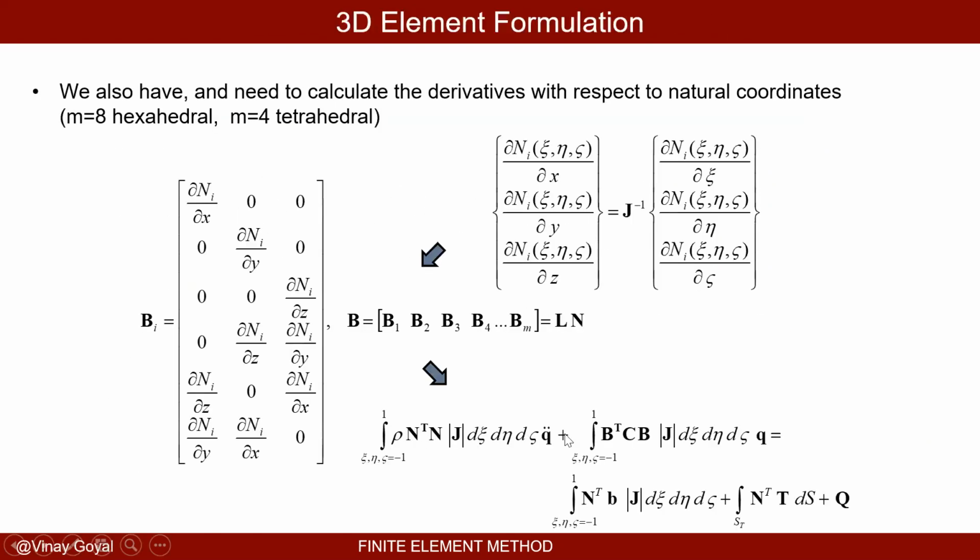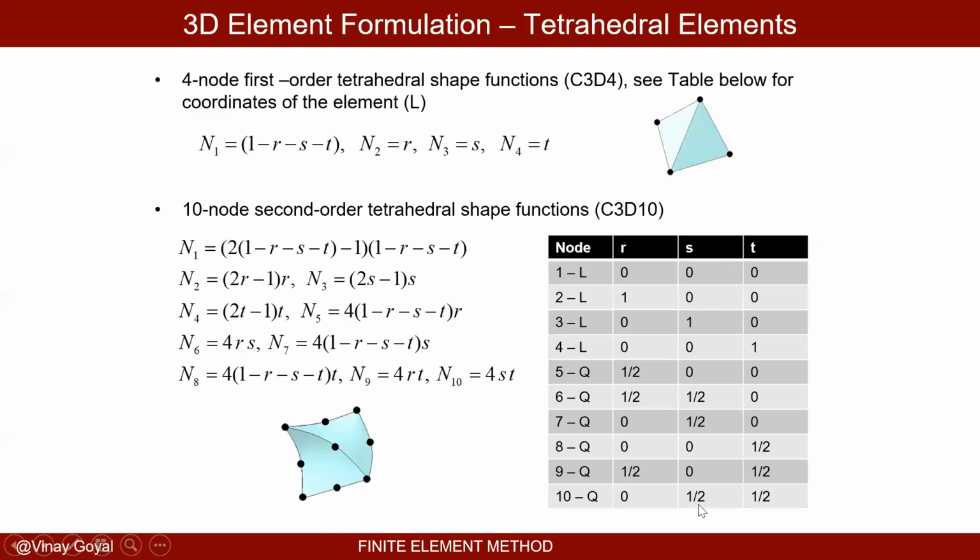So I know all this. I know the derivatives of the shape functions, so that's easy. And I'm going to use this formula here, the Jacobian times all this, to figure out what B bold is. And notice how B bold is broken up into blocks to make it easy to calculate. But everything here is fairly straightforward at this point.